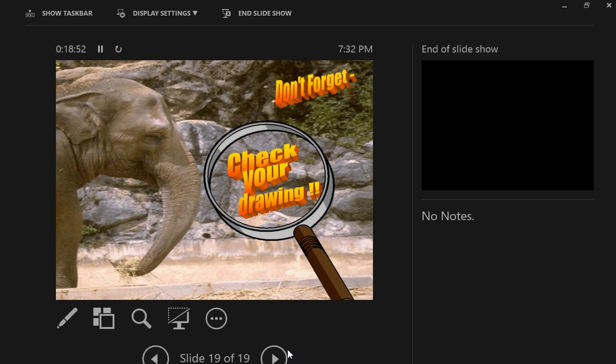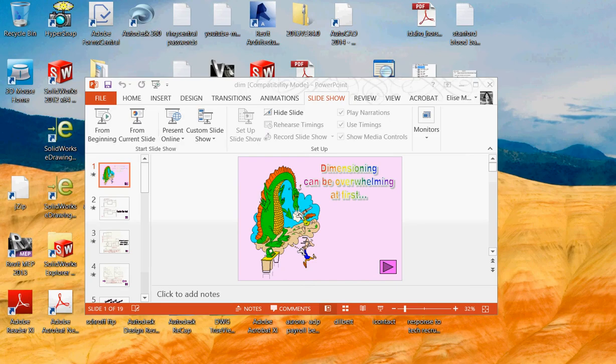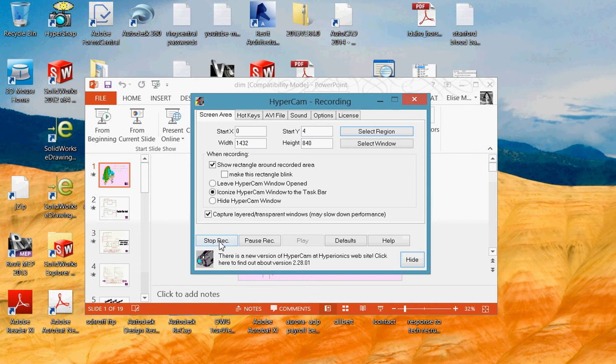Okay, so you should have 2 drawing templates, one for inches and one for millimeters. That's what we did on Tuesday, right? So you're ready to go? Both templates should be set to ANSI standard, not to ISO. You're going to use Arial font, letters too. Go through all your dimension settings, double check them to make sure everything's good. Save your template in sheet mode, not sheet format mode. Because if you put it in sheet format mode, when you open it up, you're not going to see any of your views. All right? And make sure you save your templates in your templates folder. Right? Because those are all things that are going to help you be successful.